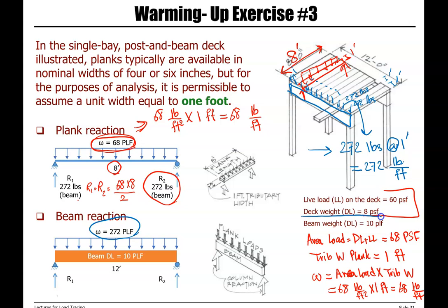When looking at the beam, we also need to include weight of beam by itself. So beam has a dead load of 10 PLF. The total load on our beam is 272 plus 10.